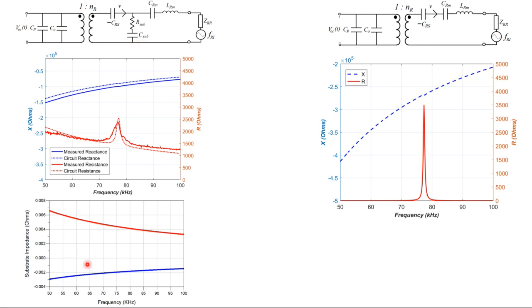So you can see over here, the blue part is the reactive part of the substrate impedance. This impedance is the impedance of this RC branch, which is modeling the damping of elastic waves in the glass medium. When these curves go into the model over here, they start creating these kinds of baselines which are being measured. Okay, and where do they come from?